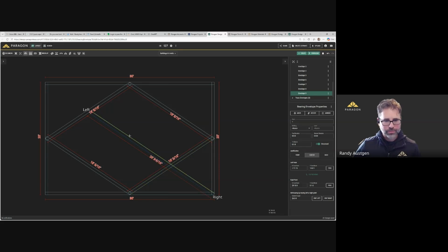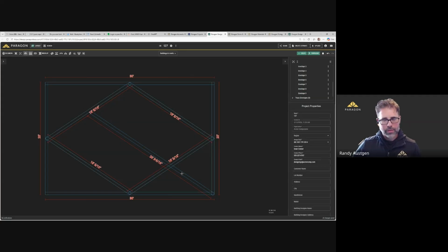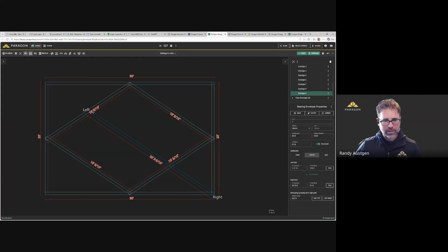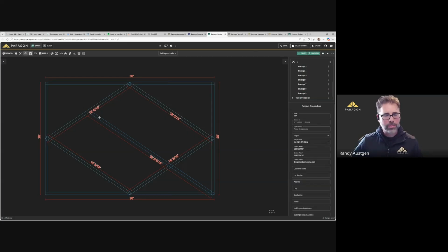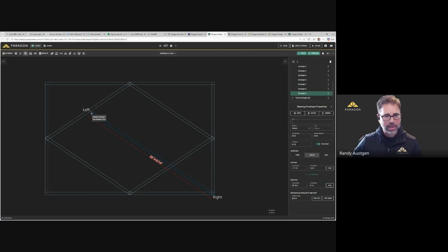And there we go. All right. So if I wanted to, essentially, this is going to be tough based on this crazy artwork I'm creating here. If I wanted to bring this line back, I'm going to turn off my dimensions for the time being. If I wanted to bring this line back to here, right? So essentially keeping that short segment, I cannot accomplish that right off the bat by using the trim extend command, but rather I can adjust, pick new points for the left and or right.